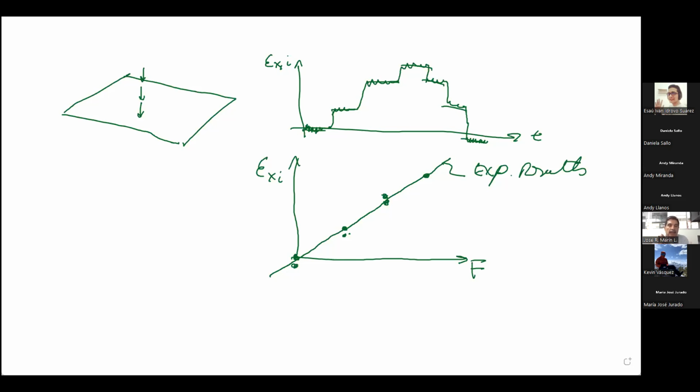You only measured 4 values of strains, right? Yes. So all you can do is compare strains at these 4 values. Just compare the strains with the theory, because you measured only strains at 4 positions. That's all you can compare. You did not measure deflection.